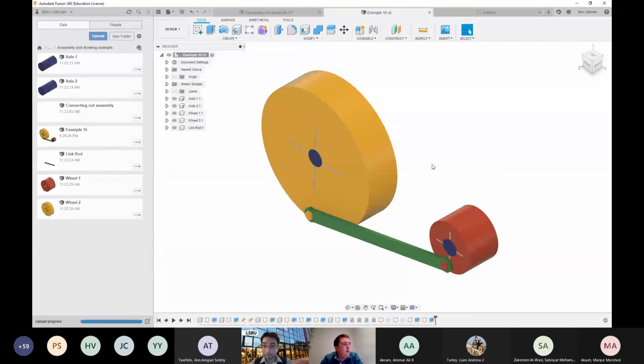The first thing I'm going to say, you'll remember this perhaps from the quiz. This system, as it's shown here, actually has a bit of a problem if I was to build it, because I haven't really got any system for fixing the wheels onto the axles. I've designed it in Fusion so that everything turns just like I want it to, but either this wheel is tight on that axle, in which case it won't turn very smoothly, or the wheel is loose on the axle, in which case I'm worried it's going to slide backwards and forwards.